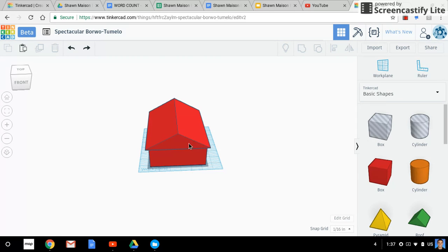So when we look here, if I'm ready to 3D print this and I want to get that STL file and download it, and then import it into a 3D printing software program, the way I do that is I go to this export function when I'm inside of the design itself. So you have to open up the design first from the home menu. So if you were on your home menu, let's just pop back there real quick, take you from the home landing page to getting a 3D file.